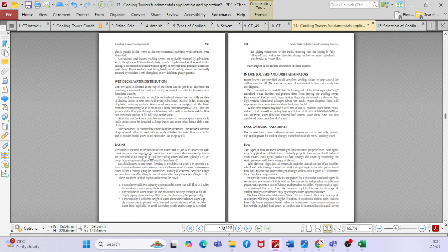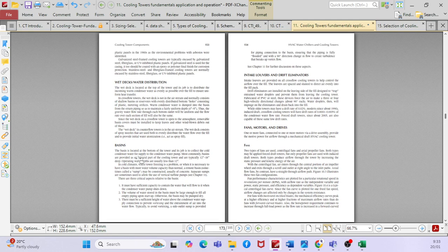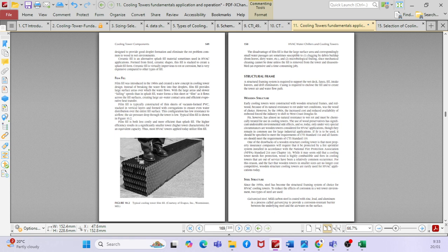This is why I wanted to ask: instead of having a jet, why can't we just have normal open-close gate valve nozzles? That is because we want to spread the water across the fill. When you spread the water, when you divide it into multiple particles, it is easy to cool down rather than one stream, same as our shower.